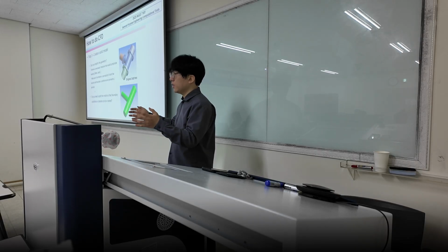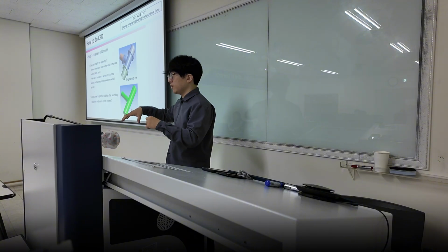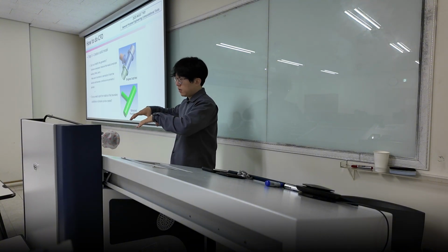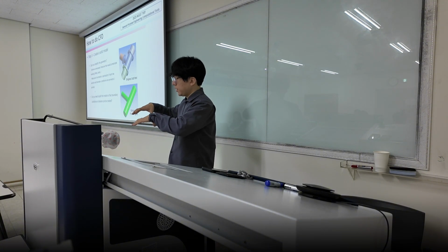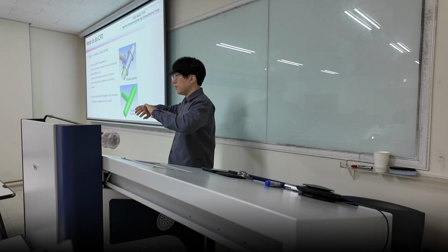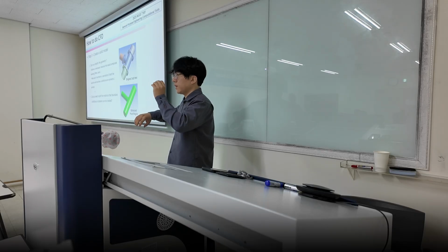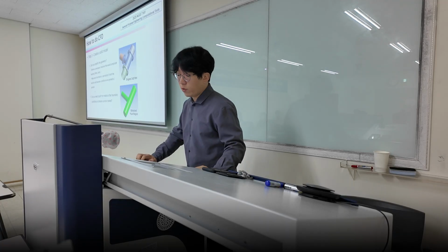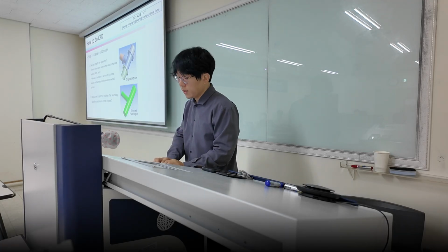Let's say you have a heat exchanger and there's header loss and the channel loss, and depending on the formulation you want to use, you can separate them and then calculate the minor losses first and then come up with channel losses, right? This applies the same way to CFD models.